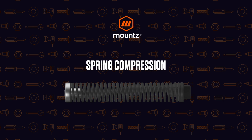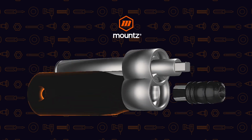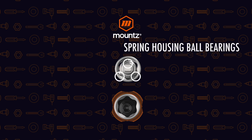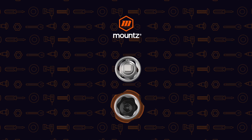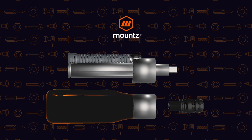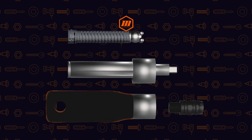In our case, we use a different method than a lot of other manufacturers, and that is the use of a radial cam within the body of the tool. We have typically a 6-lobe cam with 3 ball bearings that ride inside that cam. As the screwdriver is pressed or turned, those ball bearings push in on a larger ball bearing, and that ball bearing is what is compressing our spring.